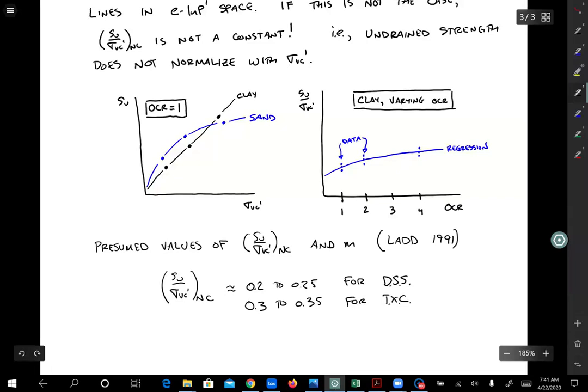All right, and there's a reason why clay tends to be stronger in triaxial compression than in direct simple shear. As you recall, the particles are like flat plates, and they tend to orient themselves with the preferred particle orientation being horizontal. So the plates don't tend to go vertical, they're this way. When you do simple shear, you're simply sliding those plates past each other, which happens fairly easily. When you do triaxial compression, you're pushing them against each other, so the strength is higher. So it's really a fabric anisotropy that's causing the strengths to be different.